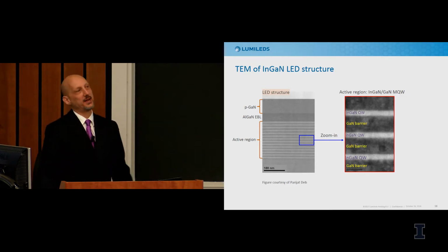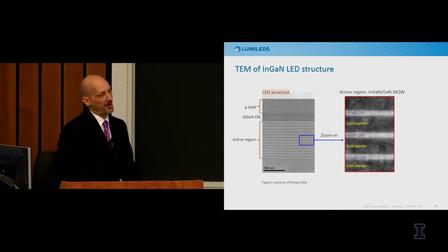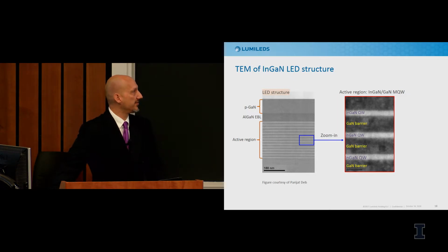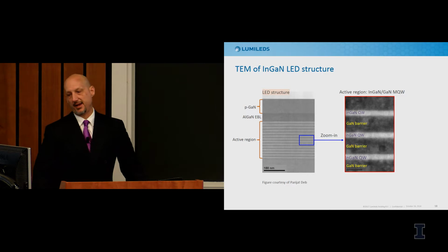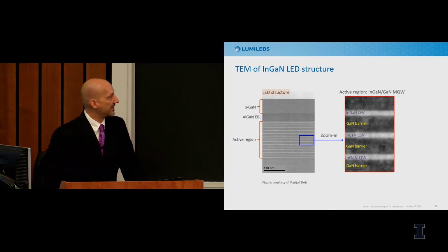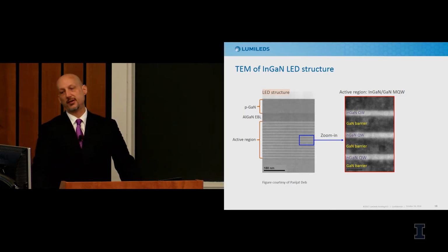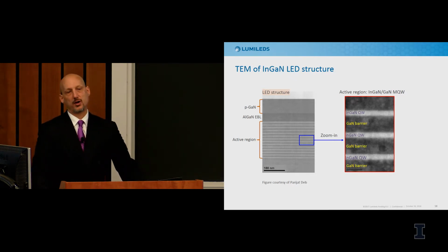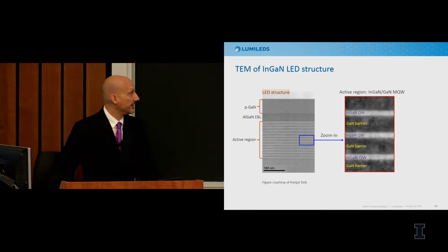But as I came to know and appreciate, they are very complicated structures. If you look, we have device layers on the nanometer scale: active regions, barriers, blocking layers for electrons and holes, all of which need to be managed in composition, strain, at the interfaces, and within the bulk of the structure.